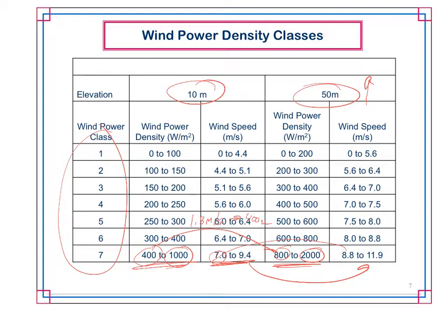This here, to go from here to here, you'll notice is a 1,000 watt increase, but how I did that was I used 2.5 meters per second. So what you're starting to see, perhaps, is a nonlinear relationship between wind speed and power density in the wind, okay? So that's an important characteristic to understand and note because that is something that we need to figure out. It is not a linear aspect.